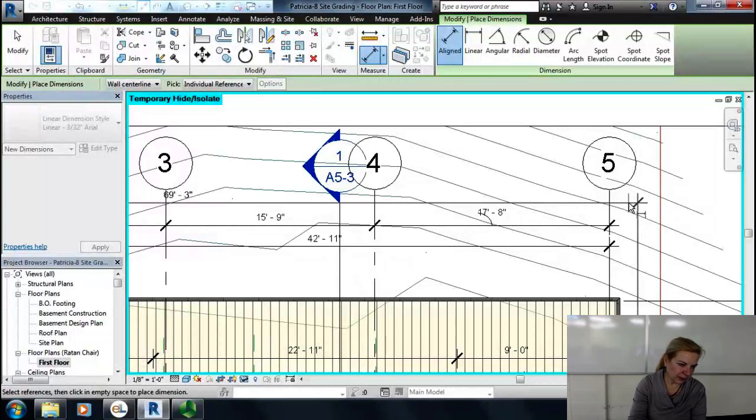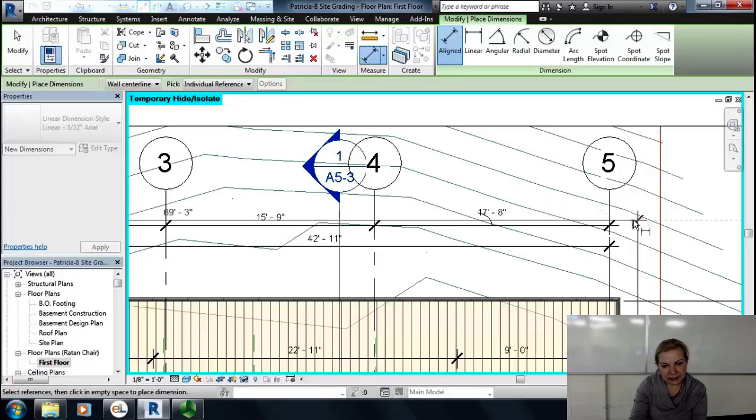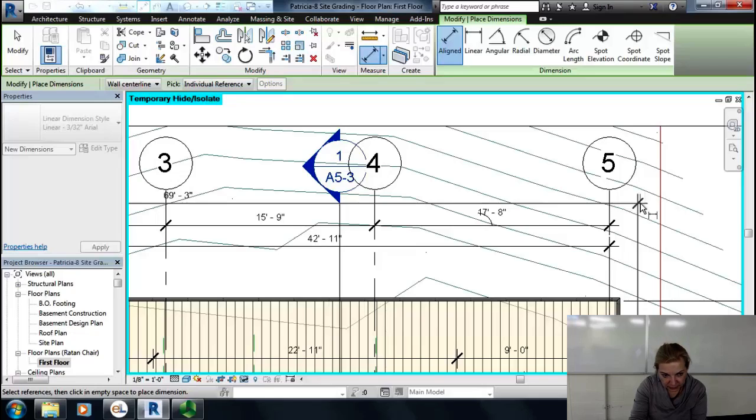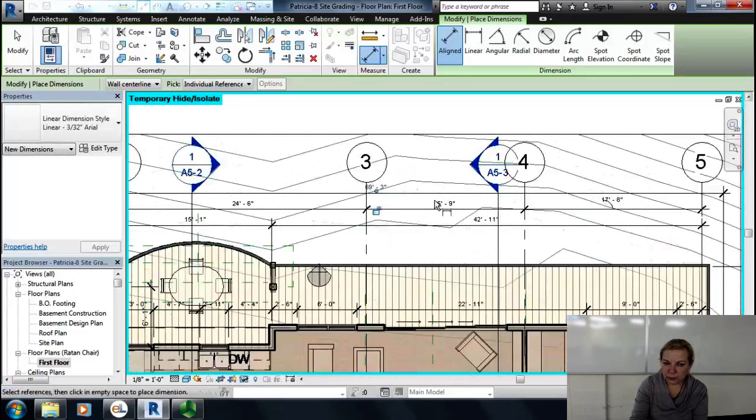Now, this is where I'm deciding where to place this dimension line, and notice that I'm eyeballing. You could create construction lines so those offsets are exactly the same, or you can place it and then move them. If I'm going too low, it's not going to be clear one way or the other. I might want to take this dimension now and move it slightly, because for the overall it really doesn't matter if it's not 100% in the center.